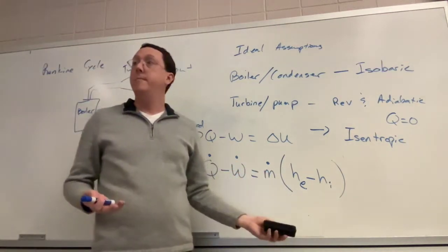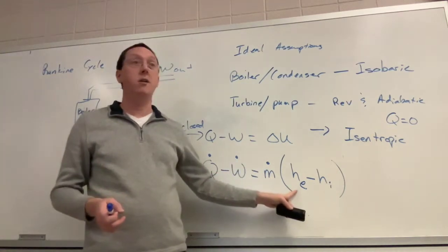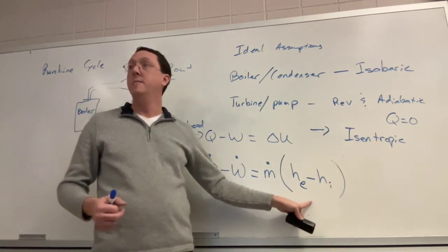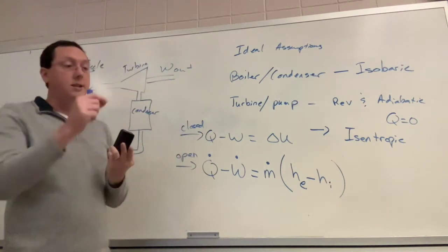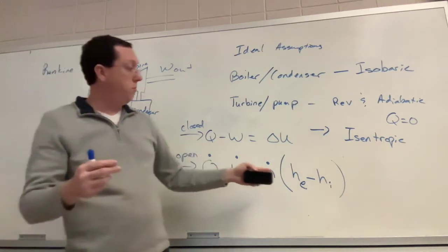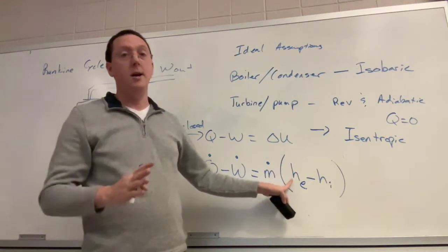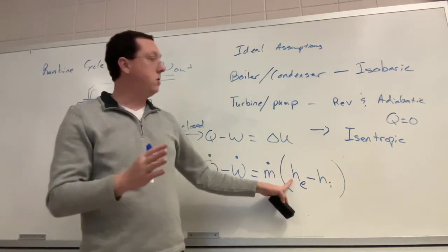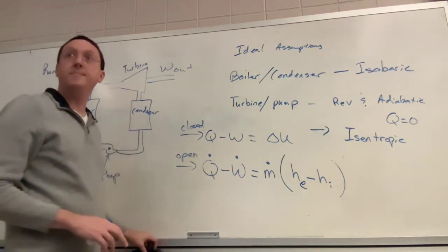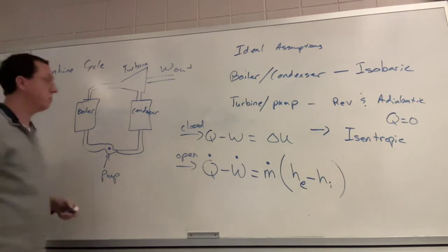The punchline then is when we're looking numbers up to get our answers, ultimately what we care about really are the enthalpies. It's all about the enthalpies for these control volume systems. So you need to know two properties at each state, fine, but if the world is good, then one of those numbers is just the enthalpy already. But in general, you need to be looking up enthalpies to work out ultimately the heats and works of things. Just trying to give you a review of things that you should know about control volume systems.